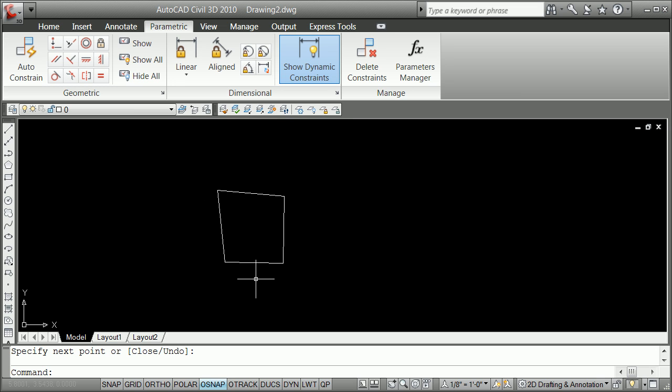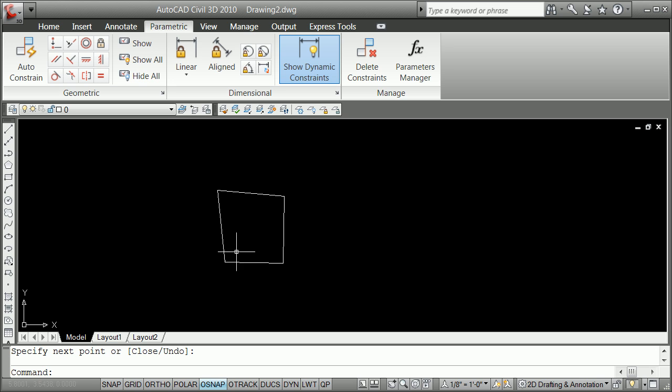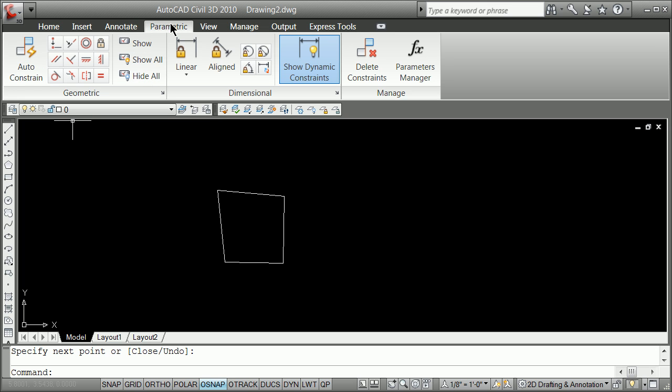So the way this works in Parametric is you draw the shape, then the constraints, and then the dimensions. Now the constraints typically are, you're going to want to start and lock down one line, at least in terms of direction, then get your angles and your distances. But before you do that, you need to let the program know that endpoints are supposed to be attached to endpoints. I brought up the parametric again.